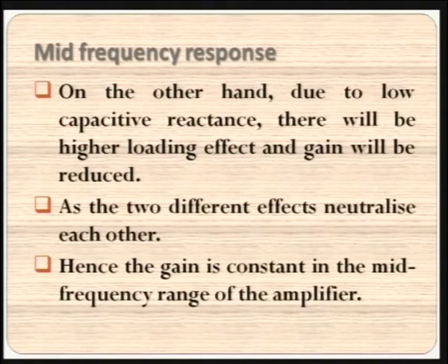So, as we guessed earlier, in the mid frequency range the gain remains constant because the two effects, the low frequency effect and also the high frequency effect due to the capacitors, cancel each other reasonably in the mid frequency range. So, the gain is more or less constant.